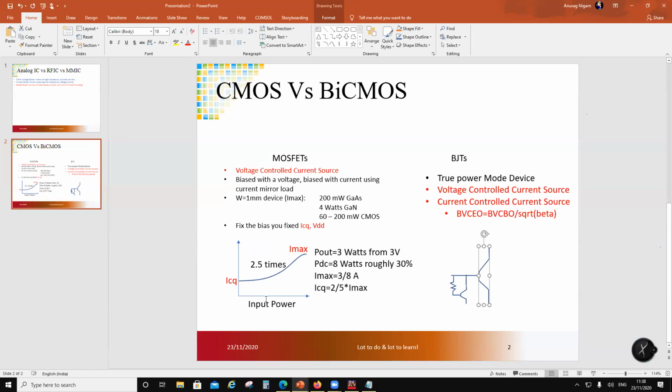So if you go to their booth and you say, show me under power, show me a mismatch, or operate it cold, this guy would blow up. RFMD would have a blown up part. You go to the IBM booth, ask them to do this with their SiGe, it will not blow up. It is very rugged. Okay, so when you are a PA designer, you are going to see these differences.